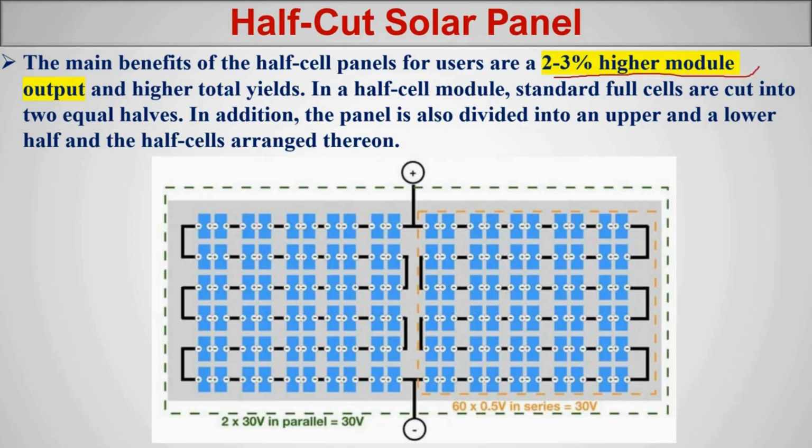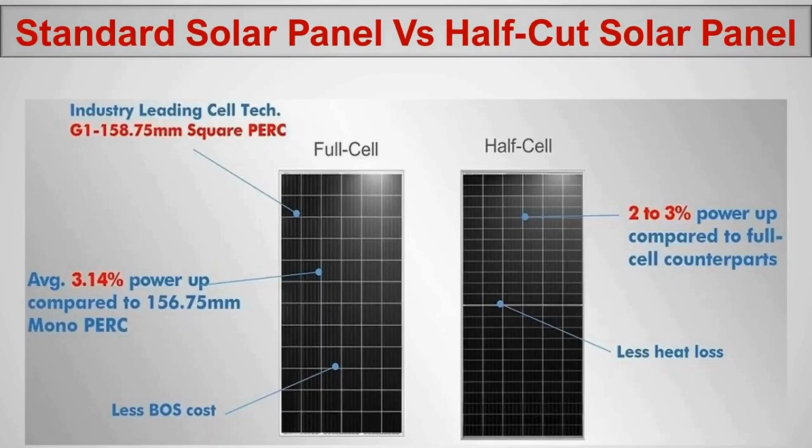Next, you can have a look here: polycrystalline, monocrystalline, half-cut technology and bifacial. We are going to study the bifacial now. The last thing is about bifacial. Bifacial means solar panels facing both sides can generate electricity. In traditional solar panels, only one side can generate electricity. The bottom side has nothing, just aluminum material, then the connectors and other appliances, the bypass diode or other diode setups, are behind the module. But bifacial solar panels use both sides to produce electricity.